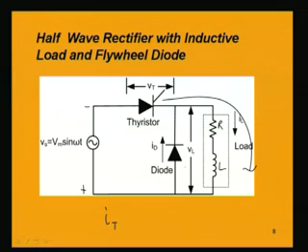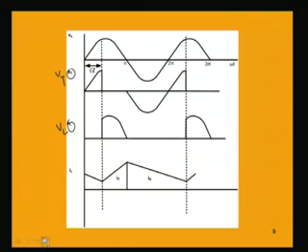it is bypassed by this diode. So, here what is happening is that if we consider the load voltage or the voltage across this load, when the thyristor was not conducting, it was 0. When it starts conducting, it becomes equal to the supply voltage, but as soon as the supply voltage enters the negative region, then the thyristor stops conducting.